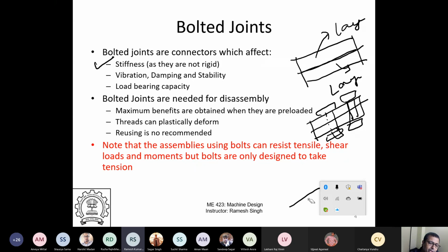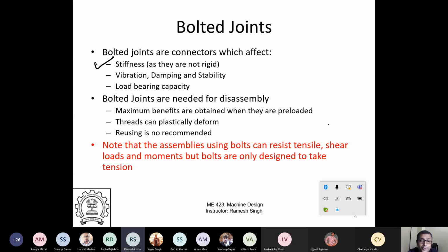There will be finite compliance because if you were to make diffusion bonded, solid, perfect bonding, it will be generally stiffer because it will be less compliant, right? Imagine I have a thick beam and two thin beams. Let's do the thought experiment. Like you have two thin beams, although in this case it's not technically so, they'll still bend about the same axis because there is perfect contact. So they'll not have two different neutral axes, but still the rigidity will be lower. So there will be compliance issues.